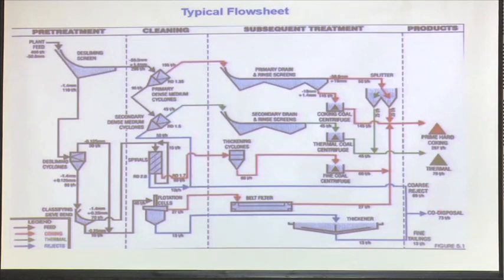If I am planning to dump it, where do I dump? What are the restrictions? What are the leachable materials, whether it will contaminate the groundwater or not, that I have to look at. Then I have to have some kind of impervious layer formed in the bottom.